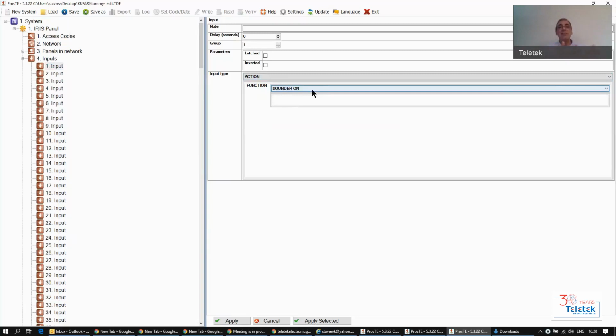Delays that are used to investigate the zone and see if it's a false alarm. You don't want to, upon receiving an event, fire or evacuation, activate everything right away, because then it makes those delays for the sounders useless. So imagine you get a fire in zone number 1 that has 5 minutes delay for the sounders. The person now, security guard, goes there, investigates, and sees the actual fire, and presses a call point to bypass the delay and activate the system into a fire mode or evacuation mode.